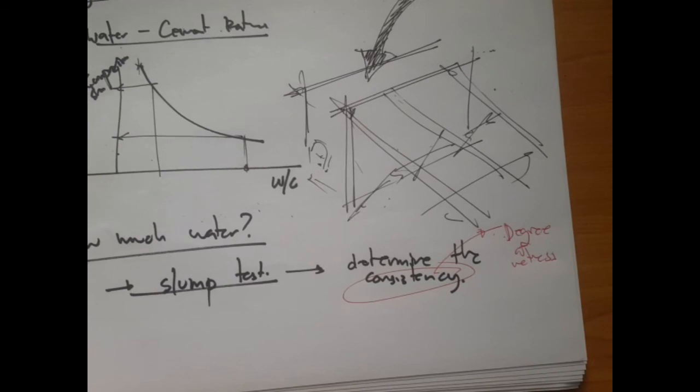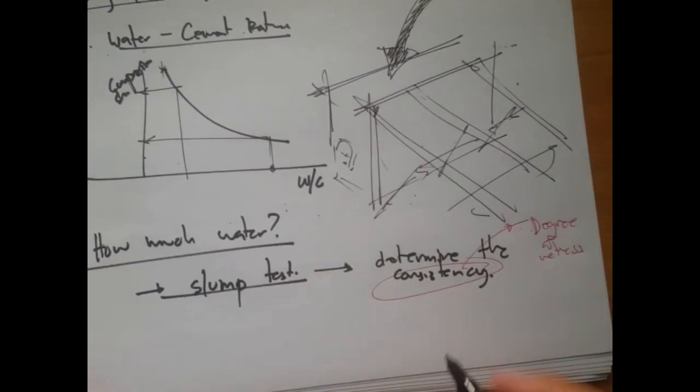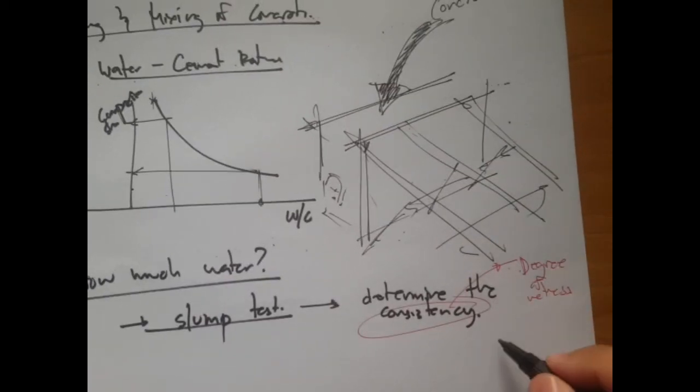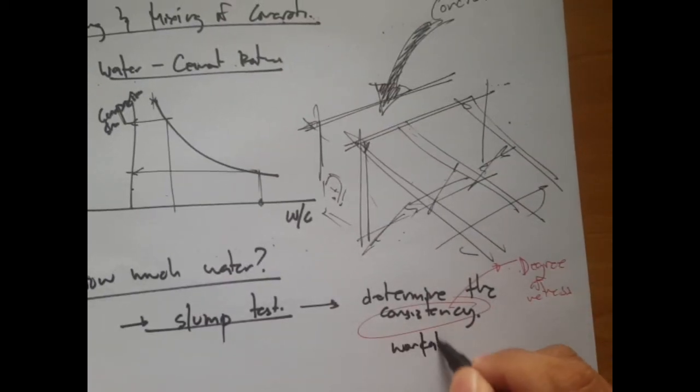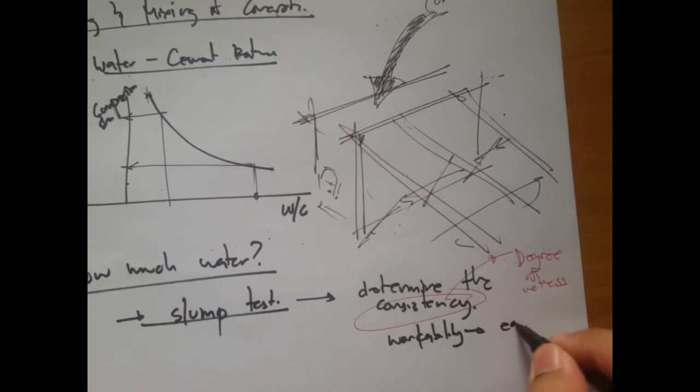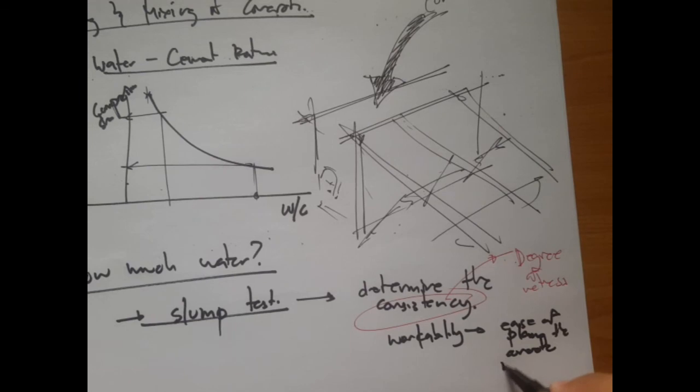Whereas another one is workability, which refers to the ease of placing the concrete mix in forms without segregation. So take note of the words without segregation.